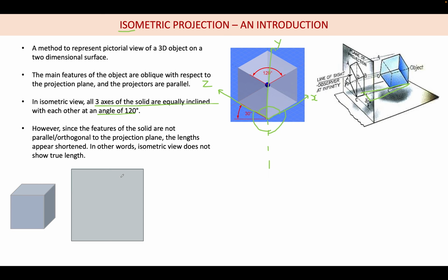Yes, so this face and this face, still this face you will not be able to see. So if I say, it will be like this. So you will be able to see this edge, and you will say this face and this face. Can you say this face will be suppose 5 mm, but what I draw here, this length will not be 5 mm. Why? Because it is at some angle, and only the cosine of that angle will be projected. So for example, theta is 30 degrees you are inclining, so cos 30 like that length will be coming. So this is 2.